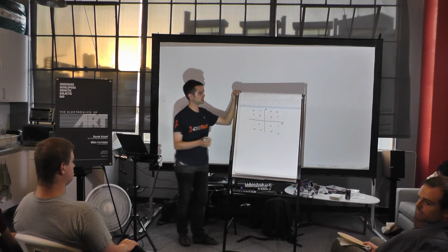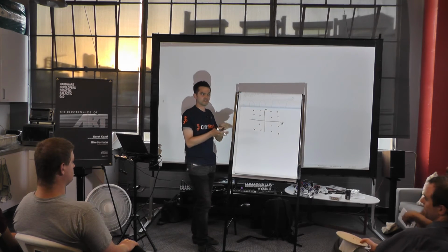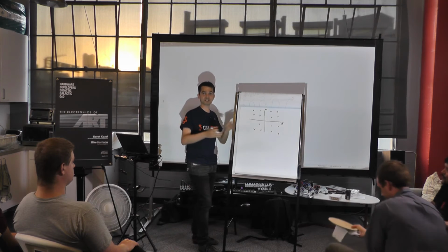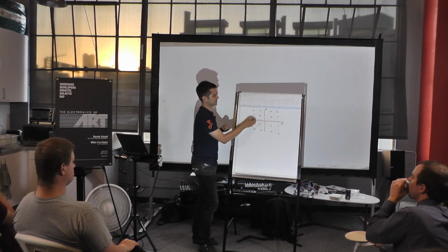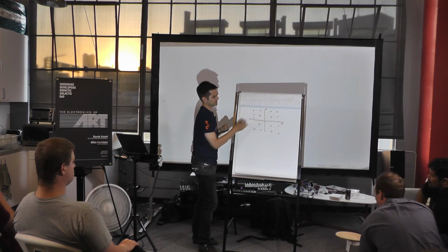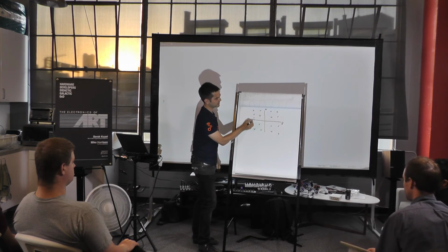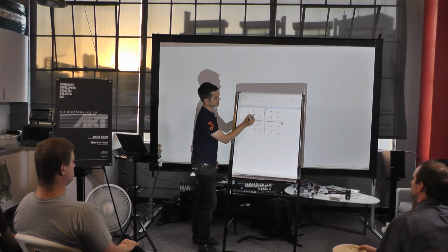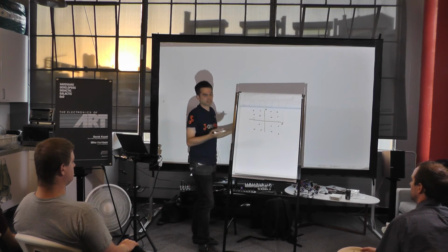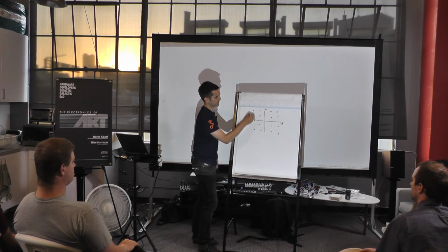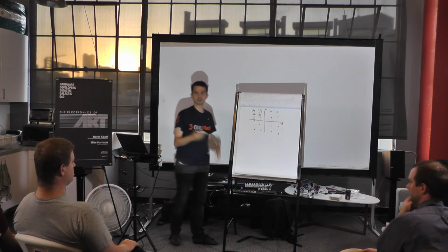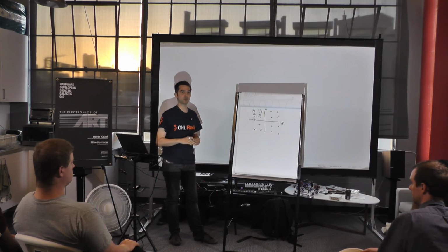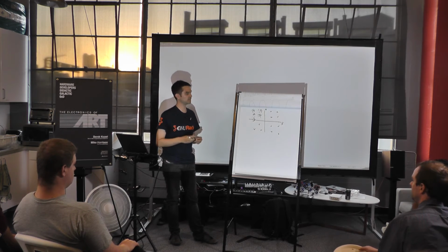Yeah. So if you get a little bit of noise, say somebody else comes along and transmits on your same frequency or very close to it, and all of a sudden, this point jumps up a bit. Now it's kind of there. Well, is that this point here? Is that point there? You don't really know. So you end up with these growing out, and all of a sudden they start running into each other, and it gets harder and harder to tell which one of these symbols is the correct one.